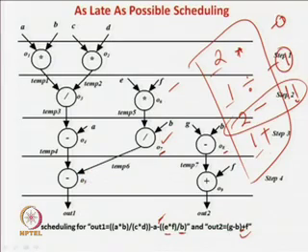So we have achieved a great deal of optimization by going for the as late as possible schedule. In this example we have scheduled everything below the end, so we have got a very good schedule where we have saved some elements. Now what have we lost? We have lost 1 subtractor. So let us see what we can do to save our subtractor. If you remember, in the case of 1 subtractor, the solution was as soon as possible, and there was no change in the adder, but the multiplier and divider we saved when going for as late as possible.